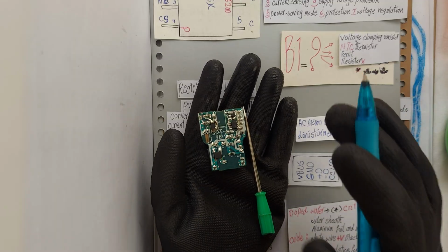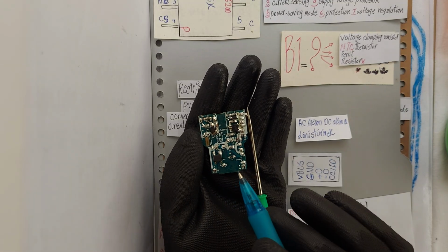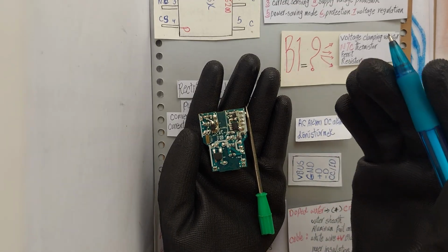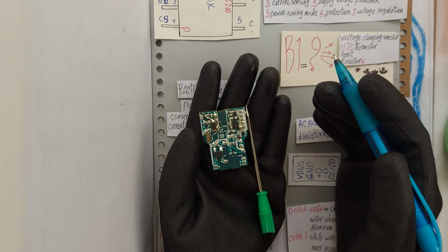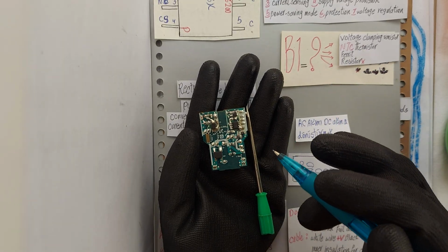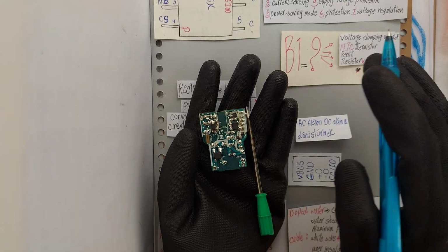So, given B1's position next to the BD1, it's more likely a ferrite bead or NTC thermistor. These are commonly used to protect the power line or suppress EMI noise. Since it resembles a resistor but lacks markings, it's unlikely to be a resistor.